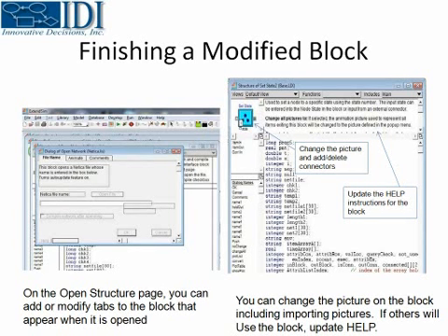Additionally, you can see there in the upper left-hand corner there's the little icon picture, and you can change the picture to make it look like something that better represents the block that you're doing. One thing that I've done with a lot of custom blocks is go to the Microsoft library for pictures and copy and paste those in there. Those work real well.